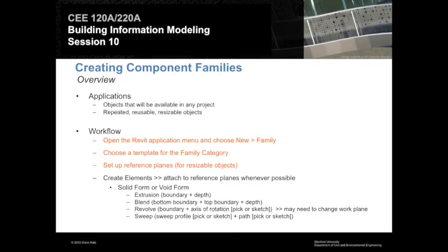But what we want to start thinking about is really, as opposed to just making in-place components, making families that are shareable and we can transfer them between lots of different projects. The reason we want to do that is that if we make them available in any project and they're repeatable, reusable, and resizable, all those good things, you get a lot of mileage out of them. So for a little bit of work, you get a lot to do.